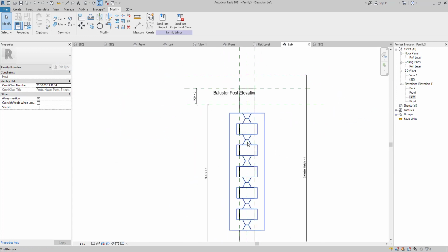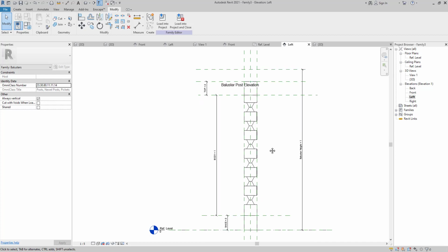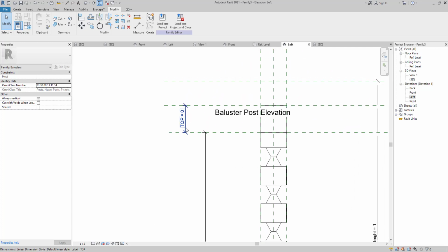All of your design, your creation, should be below your baluster height. If it won't be below your baluster height, after that, when you upload it in our project, we are going to have a visualization problem, because it's not going to consider that. So it's a very, very important note and troubleshooting, which I said now.